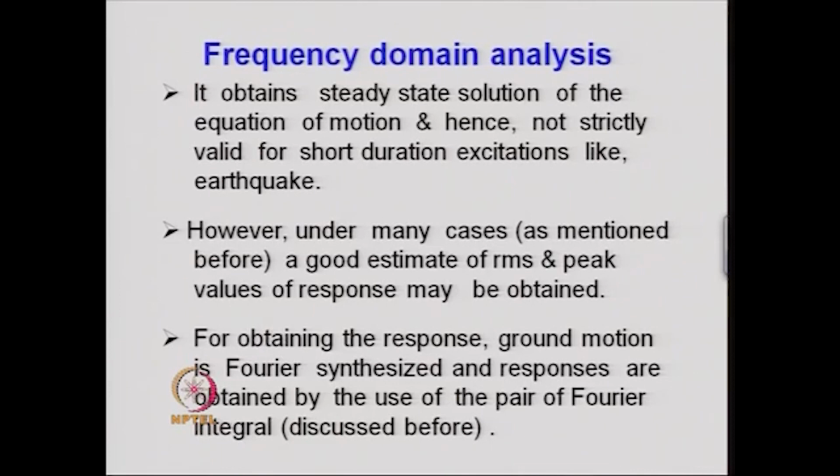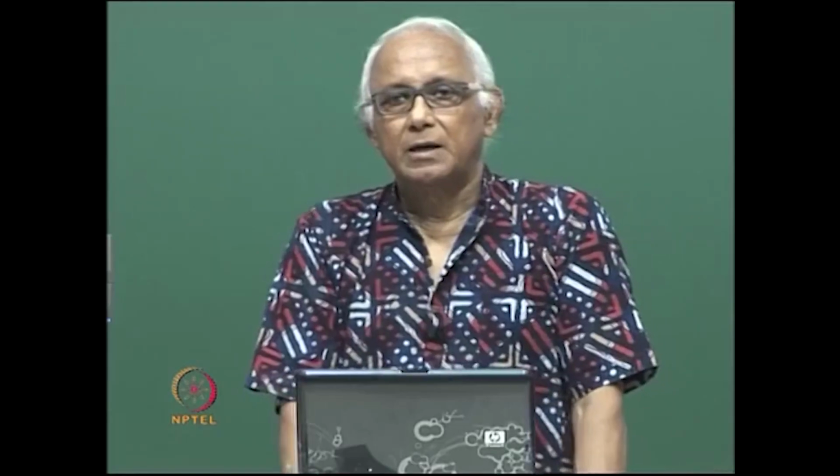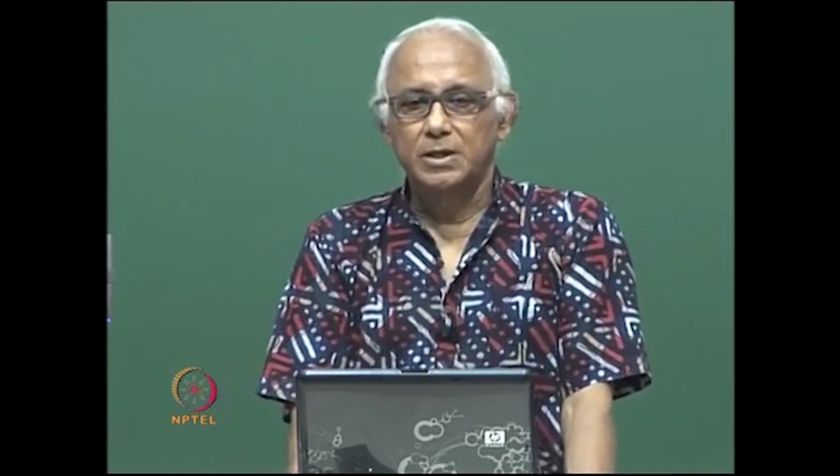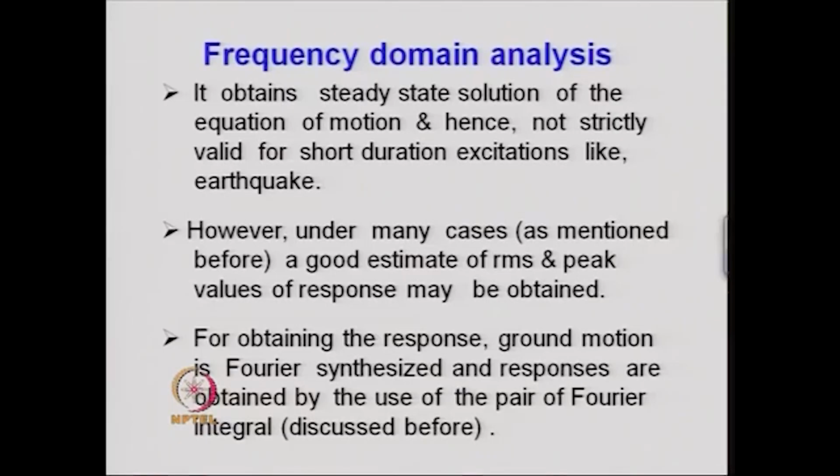In the frequency domain analysis, the analysis is performed for the structure for a specified ground motion, and in that the input is the frequency contents of the ground motion. And how to obtain the frequency contents of the ground motion with the help of Fourier series and Fourier integral we have discussed before.